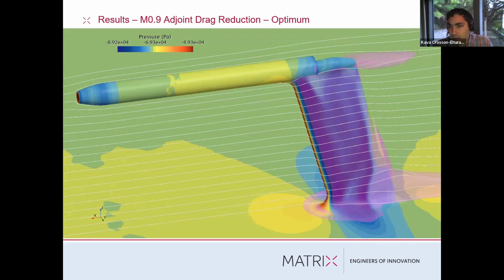So you can see that the wake is almost completely gone. There's a bit of a root wake there as well, hanging on, but the flow is far less disturbed. There's this interesting teardrop shape that forms behind the main forward Pitot tube. And that's a pretty interesting shape. I guess I wouldn't have expected that to emerge, but perhaps it's helping. It's hard to separate what's helping from what's potentially hurting here, but generally I've seen that even unexpected structures like this can reduce drag.